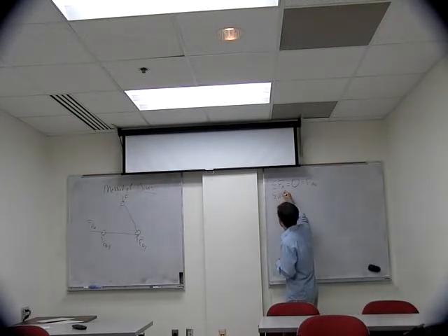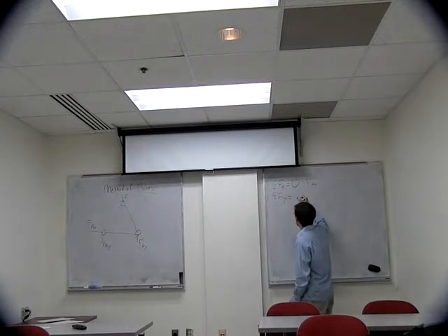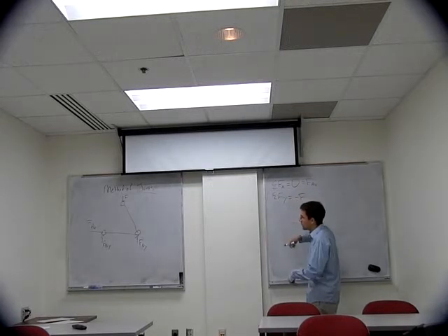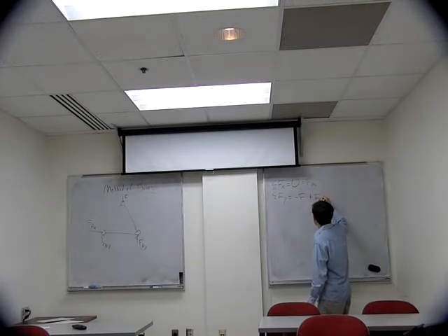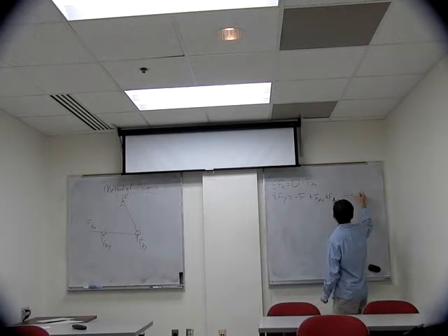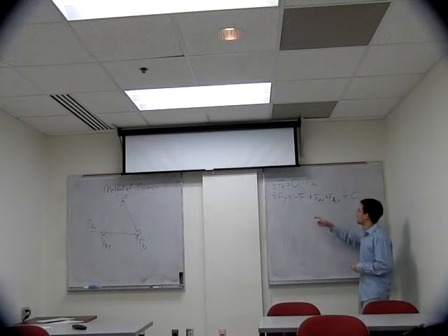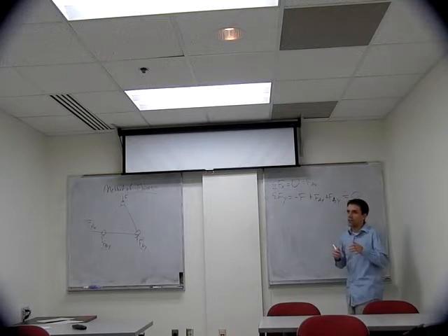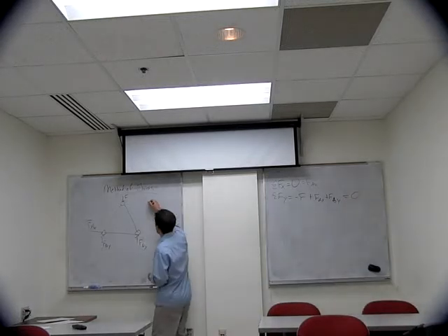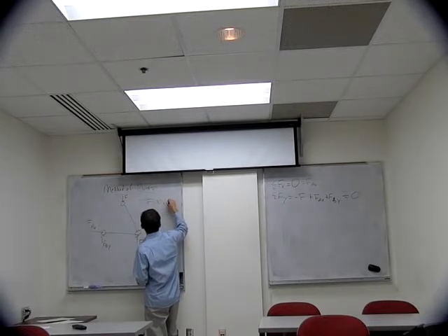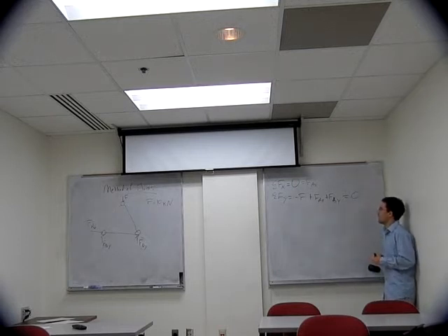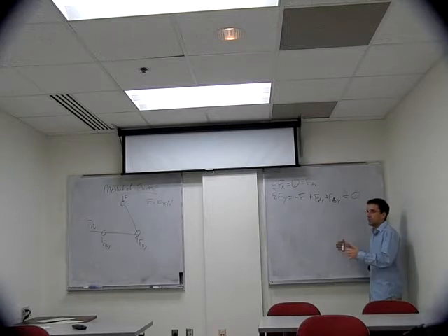If we do the summation of the forces in y, we see that we have F, which we have to have negative since it's pointed downward, plus the 2 reaction forces, which again is going to be equal to 0. But here we see that we know what F is. We know that it's an applied force. We're going to assume, for the sake of the problem, that F is equal to 10 kilonewtons. But we don't know what FAY or FBY are. So we need additional information.